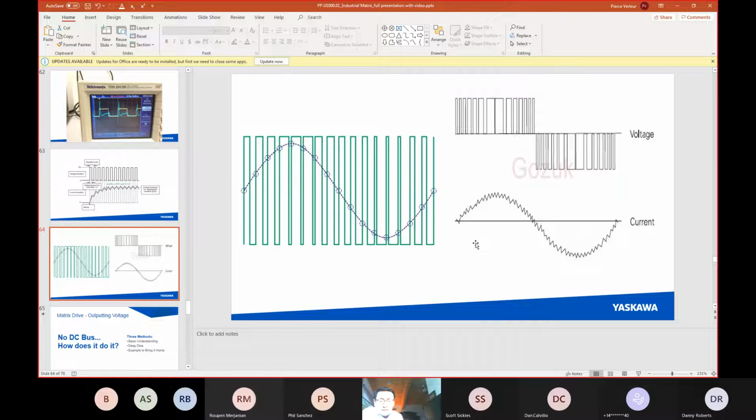And it's quite effective. I mean, we've been doing this since 1983. This circuit works. We're out there controlling a bunch of motors. Yes, there are some deleterious effects of this in terms of the noise, etc., and dV/dt to the motor. But with a close to $2 billion market for variable frequency drives in North America alone, it works. As we said before, we hang a bunch of filters on this to correct it, etc., but this is basically what we're doing. Okay.